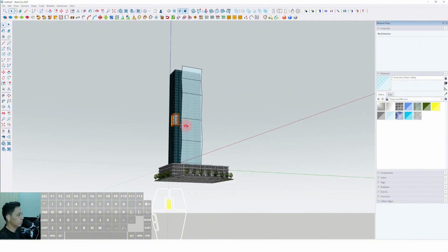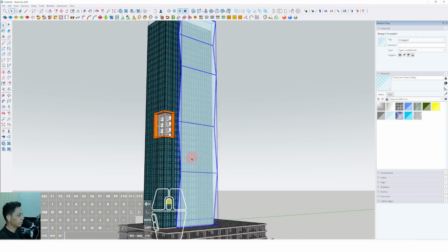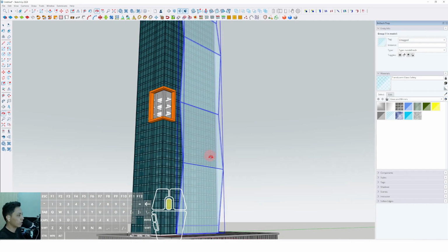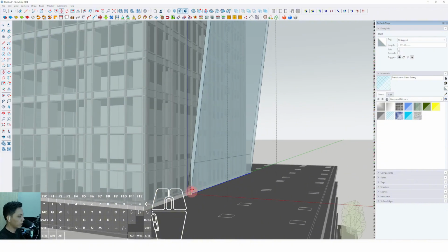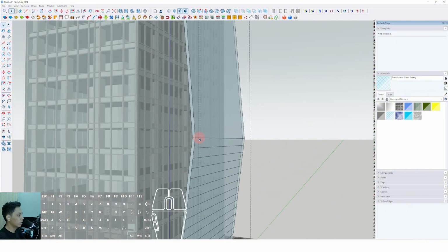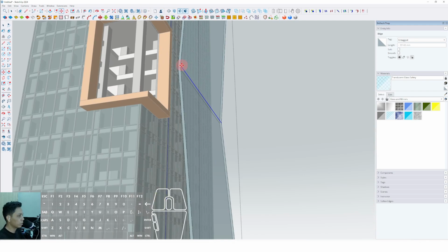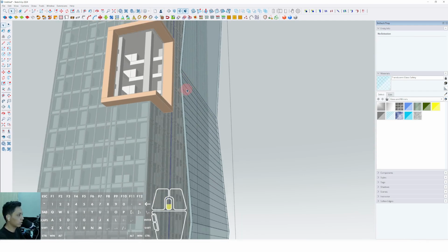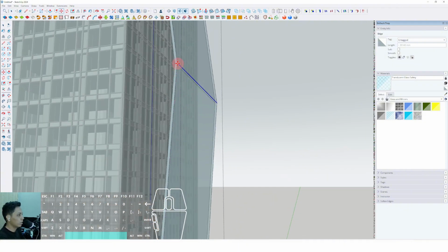Okay, well, now we can make another simple line arrangement. We can select move, press Ctrl, press this position, then we can type 20 slash enter. Okay, and also this one, you can select move, press Ctrl, press this position, then we can type 20 slash enter, and also to this another side.